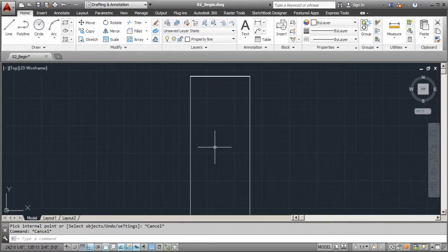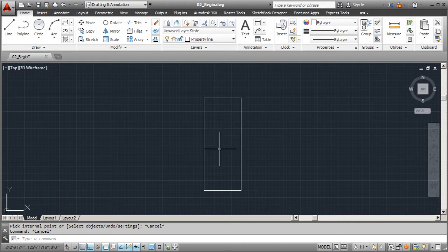You can actually go in here and draw it yourself, but if you've already started working on your design and you already have a floor plan, maybe even a roof plan, you can use those, or you can even use the building footprint. Now, in this particular design, we're actually going to use the first floor plan. One, because it has the basic footprint of the building, but it also has windows and doors in place, so I have a better understanding, and anyone who's analyzing this site plan will have a better understanding of how this building relates to the site, how you can move in and out of this building, places you can go.